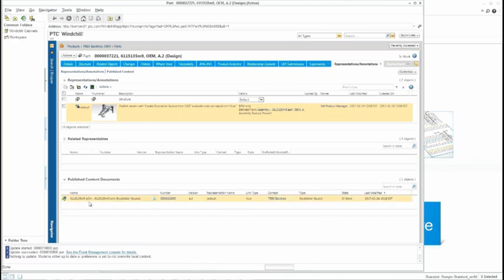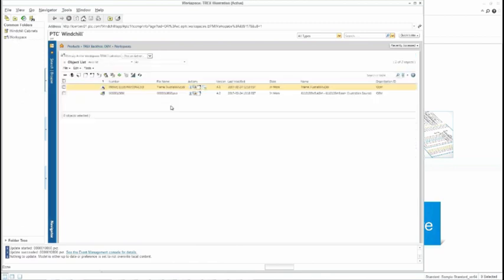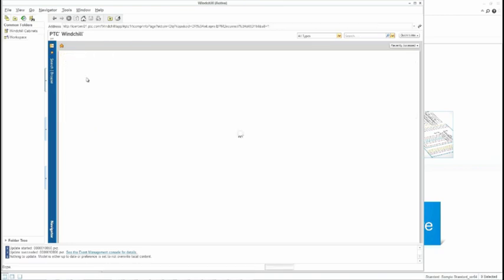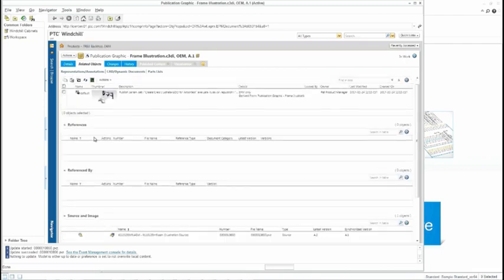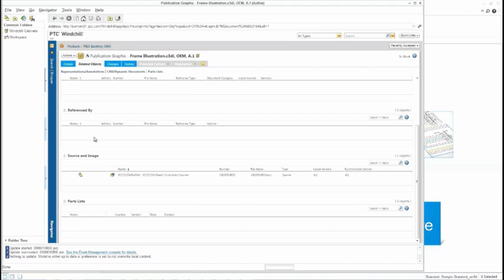So it's already gone through the approval process, and then we can see our illustration source here, and if we are on the correct version. Going back into the workspace, we can see the previous illustration that's been built, and there'll be a visual indication here once this loads up that it is out of date. If I scroll down, you'll see that little clock icon there, letting us know that the illustration source is no longer pointing to the most updated CAD. And I can see that the latest version is 8.2, but the version that I'm using for this Illustrate file is 8.1.